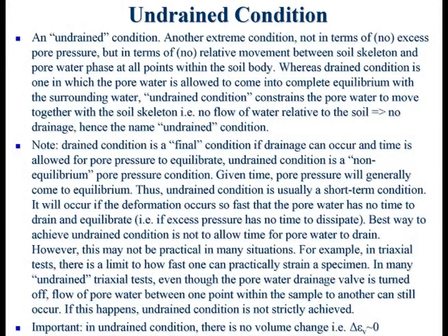So in an undrained condition, you can say, I control this soil volume inside here. The water can neither flow in nor out. That is undrained, right? But then you cannot say, at the same time, I want to control the pore water pressure. You cannot. The soil will generate its own pore water pressure. So that is the way it works. So basically, think of two ends of the rope. You're always holding one end, the soil holding the other end. It's just that you're swapping the two ends of the rope. So essentially, the undrained condition is an extreme.